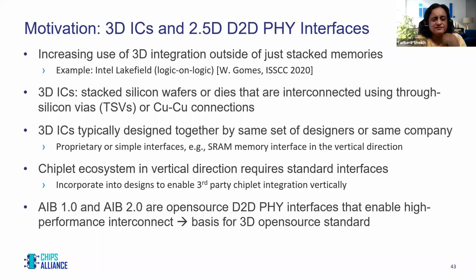So let's quickly go over the motivation for 3D ICs and why we're looking at 3D integration and 3D standards for die-to-die interfaces. As Laguan said, there is now some interest in going vertical in terms of stacking dies, and there is an increasing use of 3D integration outside of just stacked memories. We can see this in recently published material. An example I listed here is the Intel Lakefield processor that was published last year at ISSCC, and that is a logic-on-logic type of platform.